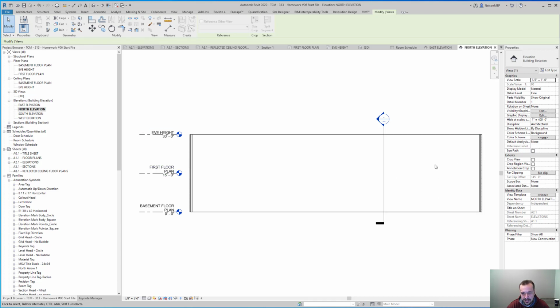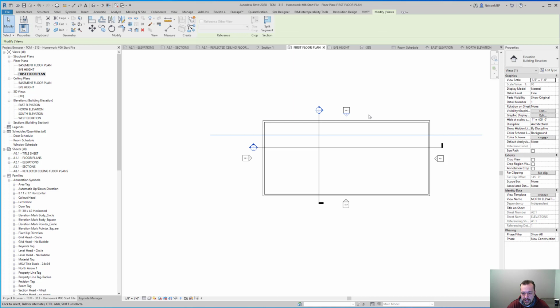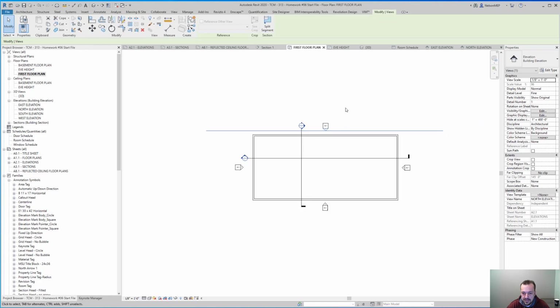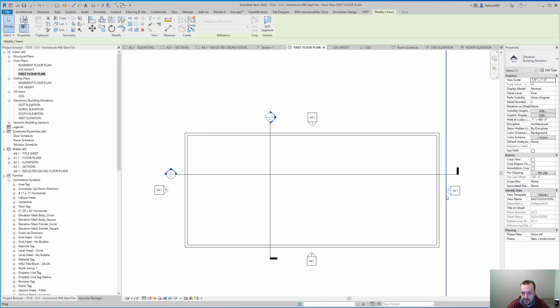Now I'm actually doing a section view because I pulled that back. And so on my item here in my floor plan, I want to be sure when I click this section that it's all the way back here. All right. And there's a certain depth that this comes with. So if you're finding that you can't view the elevation and you're in the section view, it has to do with this line not being lined up correctly.